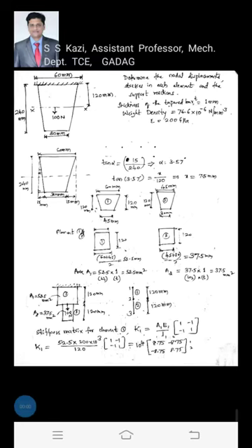In this video session, let us learn how to solve the problem on tapered bar subjected to point load considering its self weight. Let us determine the nodal displacement, stresses in each element and the support reactions for the tapered bar considering its self weight subjected to point load using elimination method and penalty method in the finite element method.